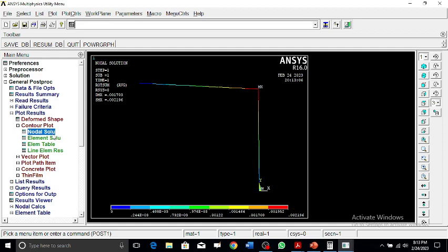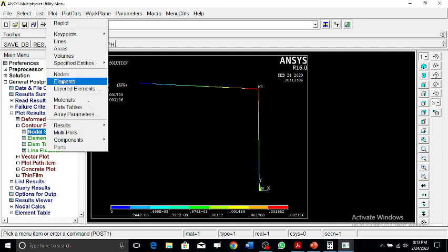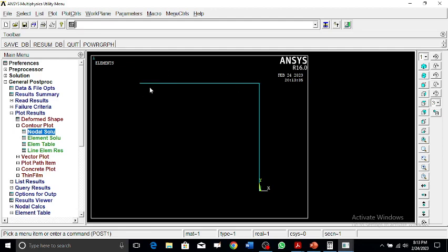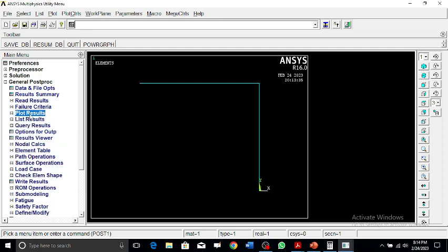And as we have done this, he has asked you, but still we can take further outputs from Ansys. Basically we can calculate the bending stresses, because as the force is applied, pressure is applied over here, it is going to bend. So this will have bending stresses at the top and bending stresses at the bottom, and because it has the capability to undergo axial deformation, there will also be axial stresses. We are not being asked, but we can do that.